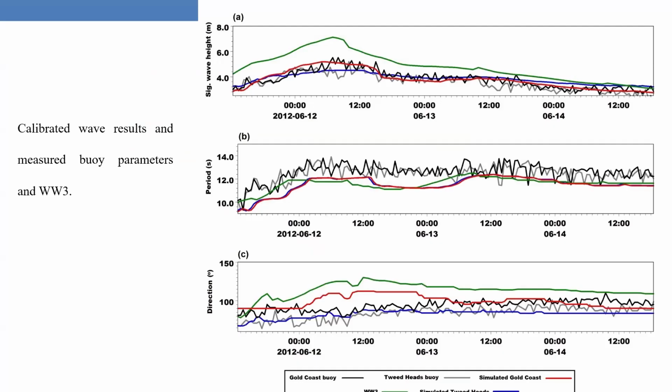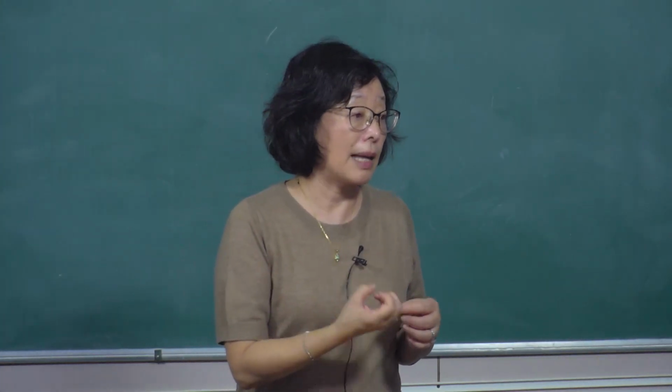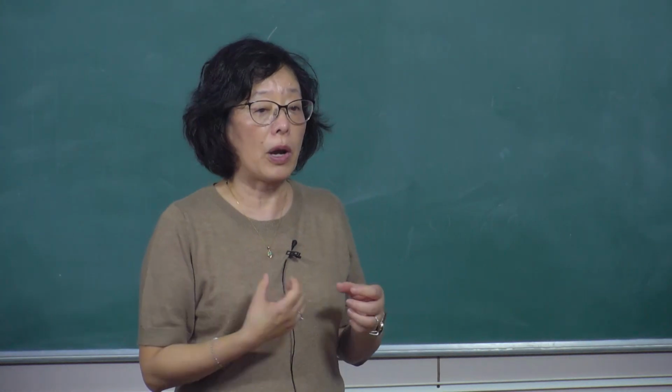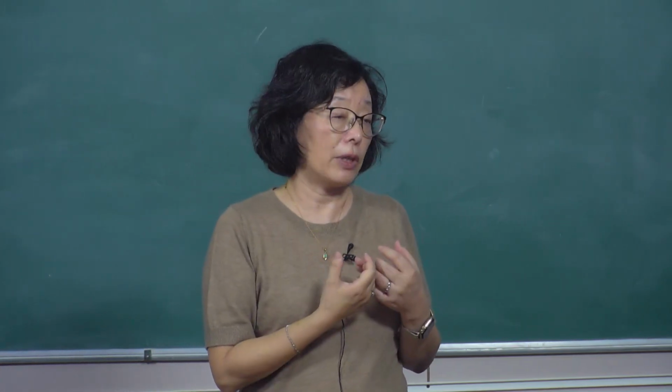And when we come to the calibration of the wave result, if you have done that, you know there are many parameters you are able to tune: break index, whitecapping coefficient, bottom friction, the sediment size for the bottom. So all of those parameters you are able to tune and then try to get the best fit.